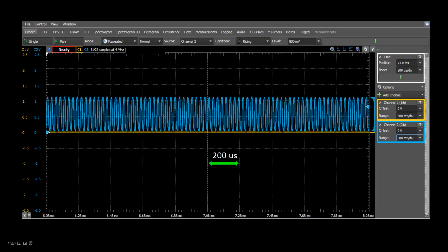Lastly, this is the feature most interesting to this lab, which is the carrier AM modulation. All bits of the data are amplitude modulated, but it is best to use the long preamble signal to look at the modulation such as shown here. On the 200 microsecond time scale, the AD2 scope data display carrier waveform in details. As shown in the previous video, Fourier transform of the data shows a fundamental carrier frequency of 38 kHz for this remote. Your remote may have a different frequency.